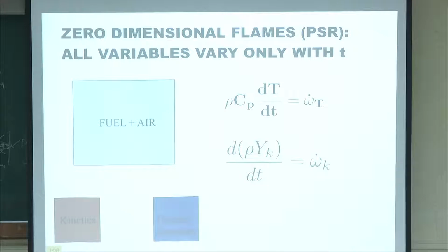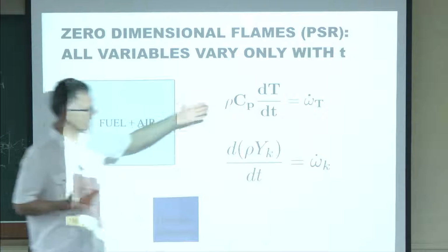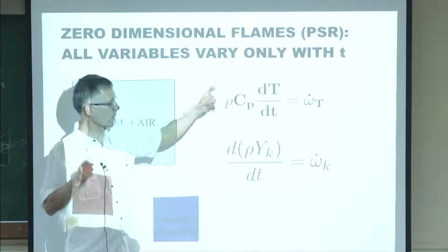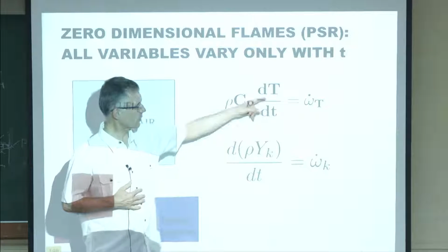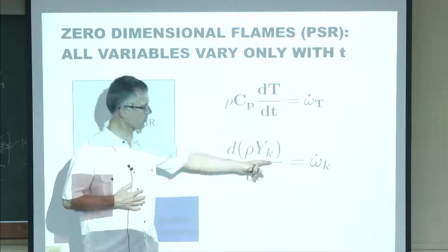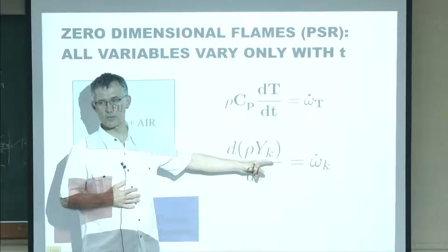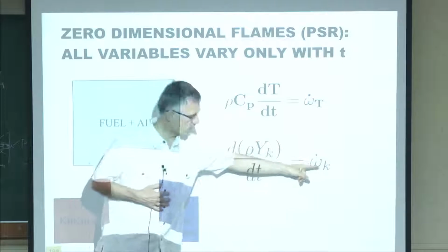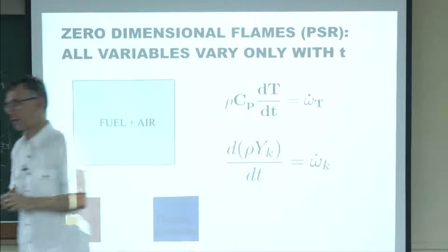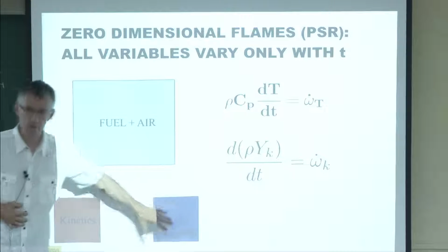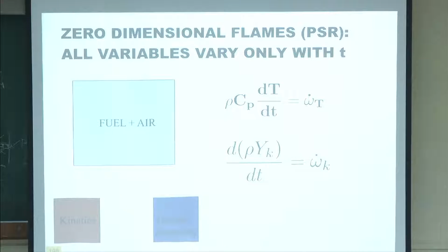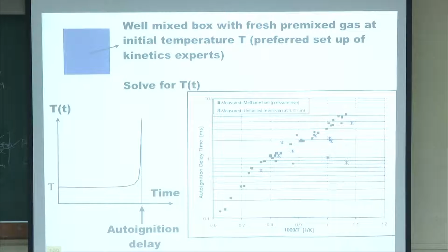Well, because even in that case, the equations of conservation are still complicated, because remember, you may have 10,000 reactions here. So you need to solve the temperature equation, and you need to solve the mass fractions equations. There are n of them. And the expressions here are complicated. So which kind of problems do you do when you do that? Well, you have to include the kinetics and the thermochemistry. That's thermodynamics. And which kind of results do you hope to get? Well, it's what we call autoignition times computation.